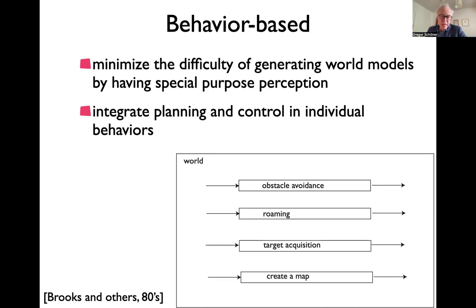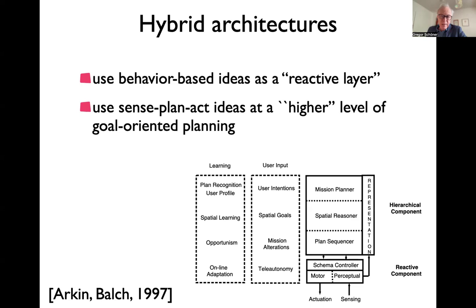And this is an influential idea that is being used a lot, and typically they are combined. That is, the state of the art is that a lot of the machines have these kinds of behavior-based controllers here. It's called schema-based at a low level. This really does the detailed action on the current sensor information. But they might also have a more classical sense, plan, act architecture on top that does classical programming and planning, which again wasn't covered so much in my lecture, to then modulate this low-level stuff.